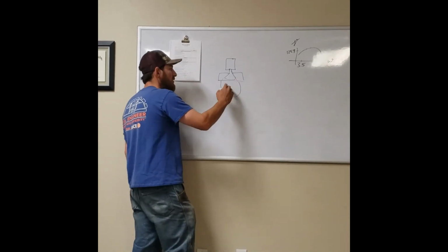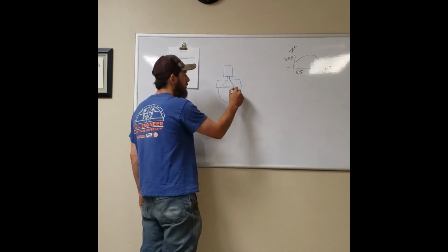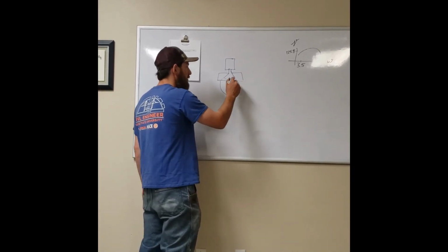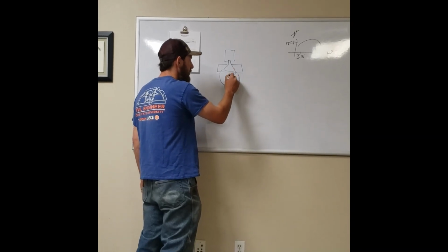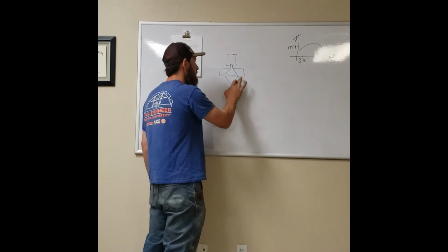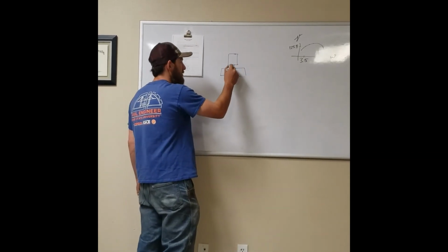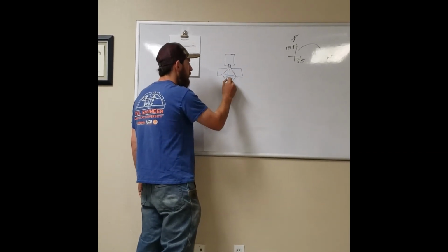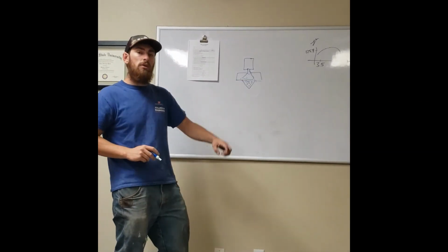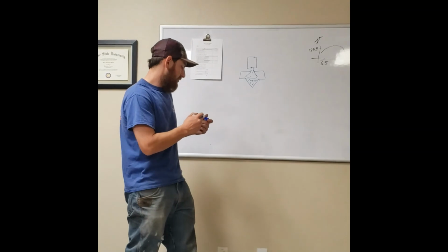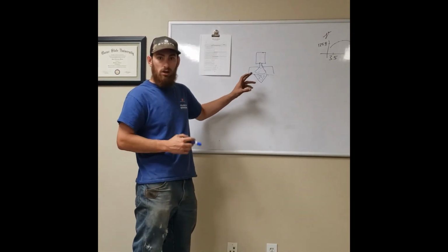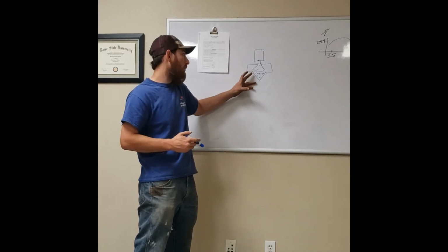Now the problem is, if the hole comes out too far, for this whole little section in here where it's concave out, the sand's not going to fill that. So I need to be careful and try to dig my hole basically as straight as I can. I'm going to have sand come all the way down and fill up the whole hole. I'm going to save all this material that I took out, and I'm going to figure out how much sand exactly filled the hole. That'll give me my volume after I do a couple of calculations to figure out exactly how big this hole was.